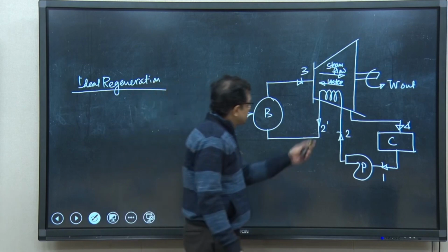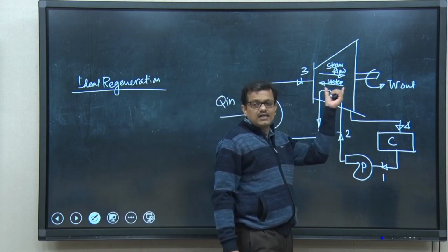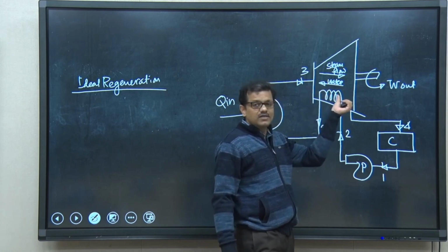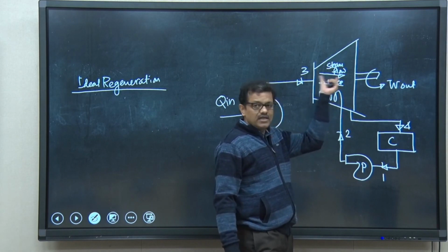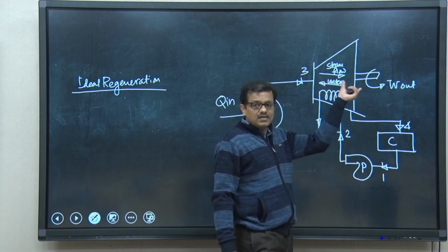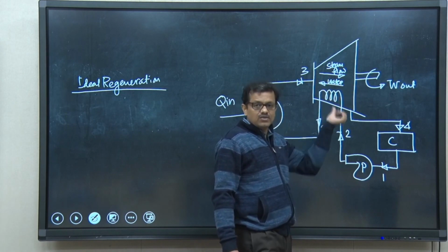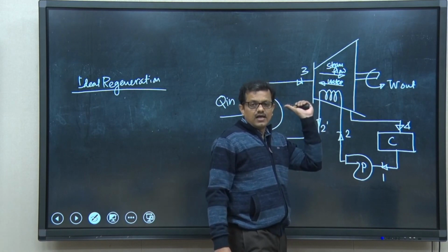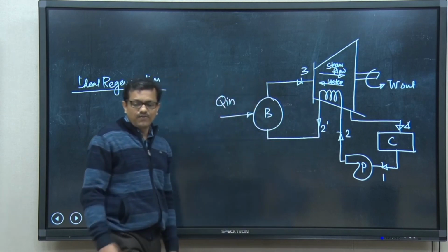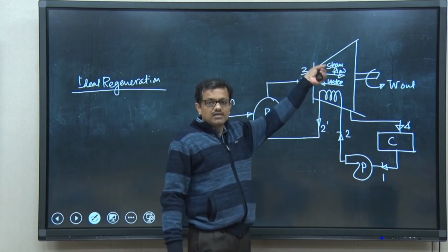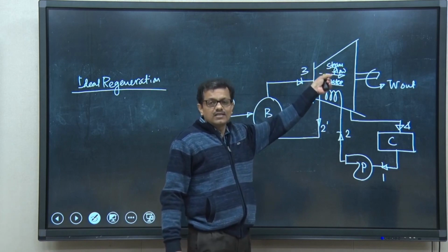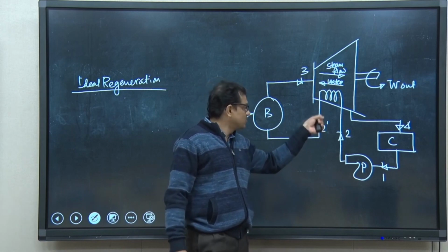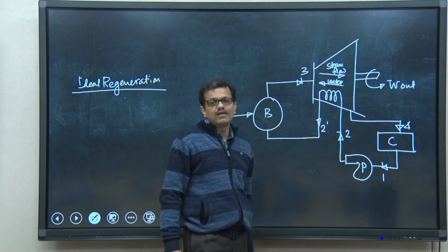You have studied in the heat transfer course that this is a counterflow heat exchanger type. So, one stream is flowing, that is steam is flowing from left to right, while water is flowing in the reverse direction, and while these two streams flow in this device, because steam has high enthalpy, they will exchange heat, and as a result the water which comes out of this coil will have high temperature.